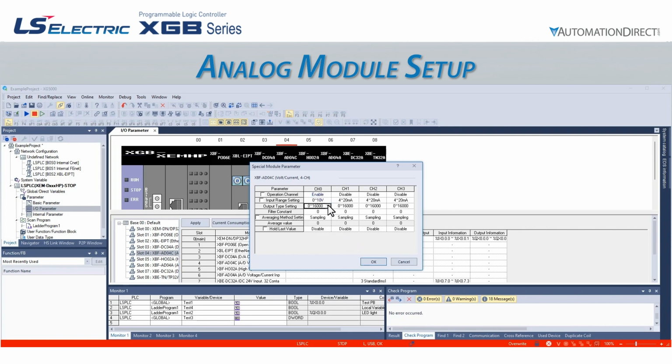The output type setting deals with what the module outputs to the PLC CPU. This will vary based on the resolution of the module. Our module is a 14-bit input module, which would be a range of 0 to 16,383 counts. The software limits the output to a 16,000 count range, but you can shift the upper and lower limits of the range, or even have the value converted to a percentage of the range. These numbers will change if you have a different resolution on your input module.